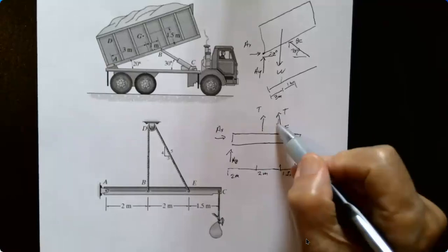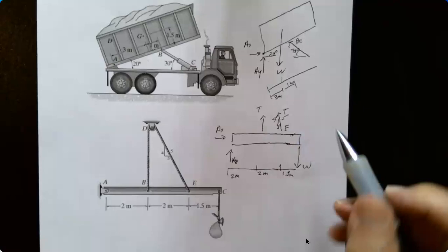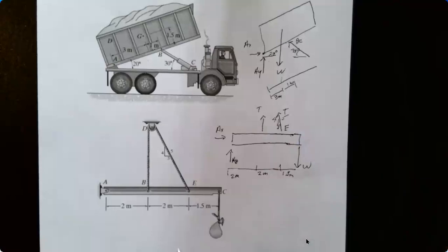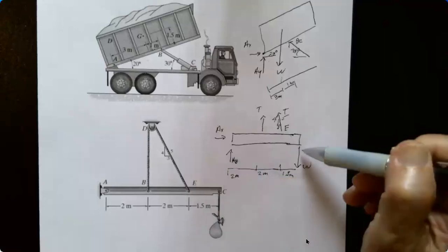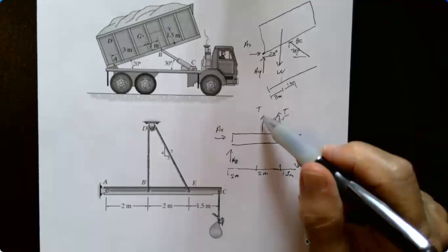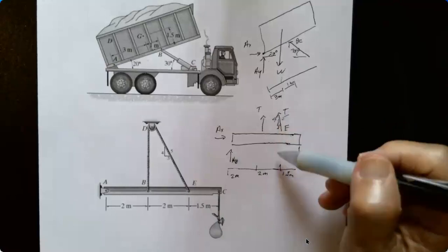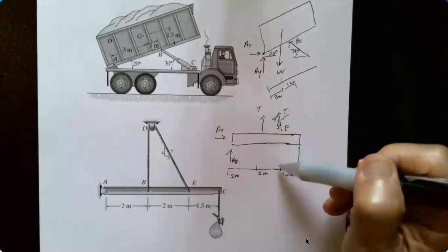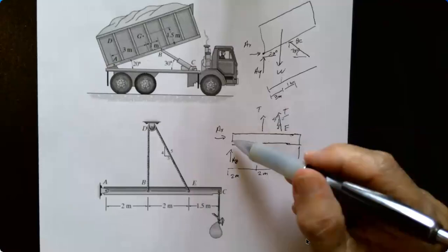And the solution then, once we have this as a free body diagram, is really very simple. Take moments about A, we have this W, and then we have T directed straight up, and then we have T again, which is going to be 4/5 of T times its moment arm. And you solve for T, taking moments about A.